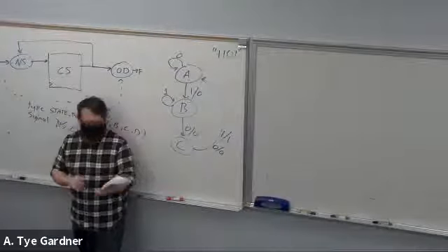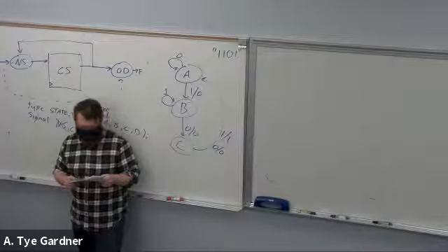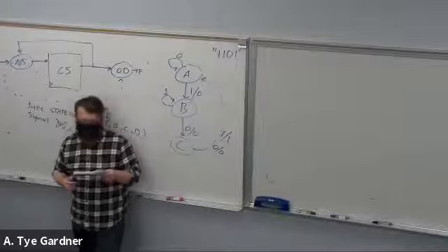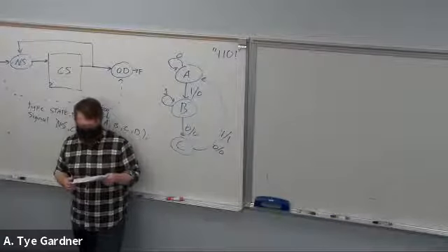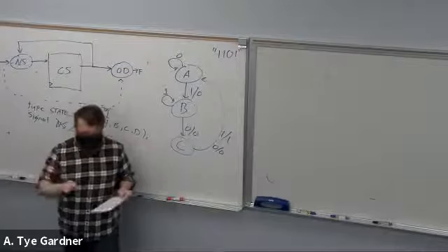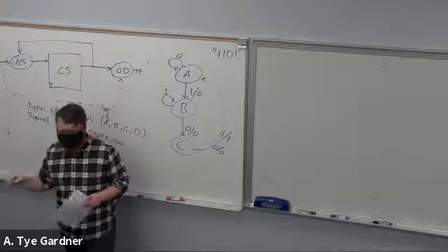So a lot of people put T flip-flop, totally fine. Number 8, the reset is synchronous because it's inside of the if statement and the rising edge of clock. B on that one, the 2 devices are a MUX, which is the one that I definitely wanted you to get.